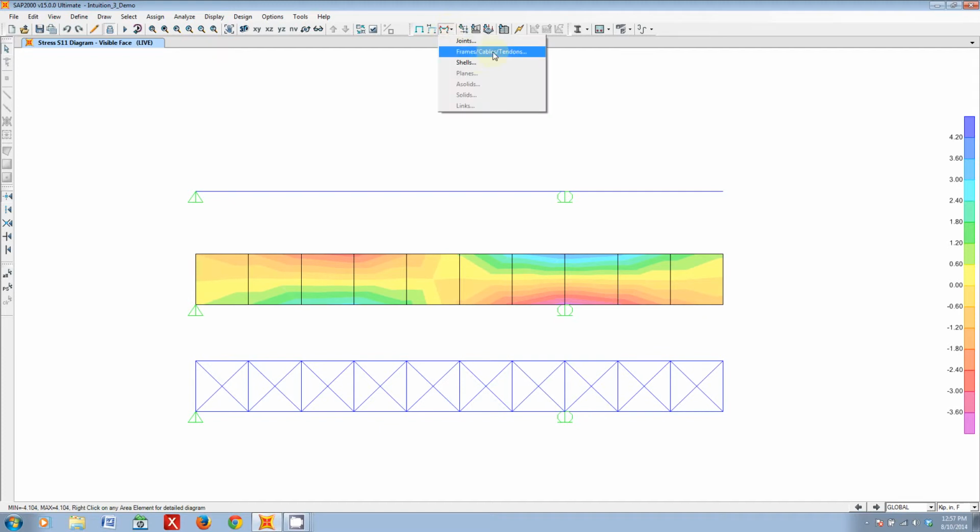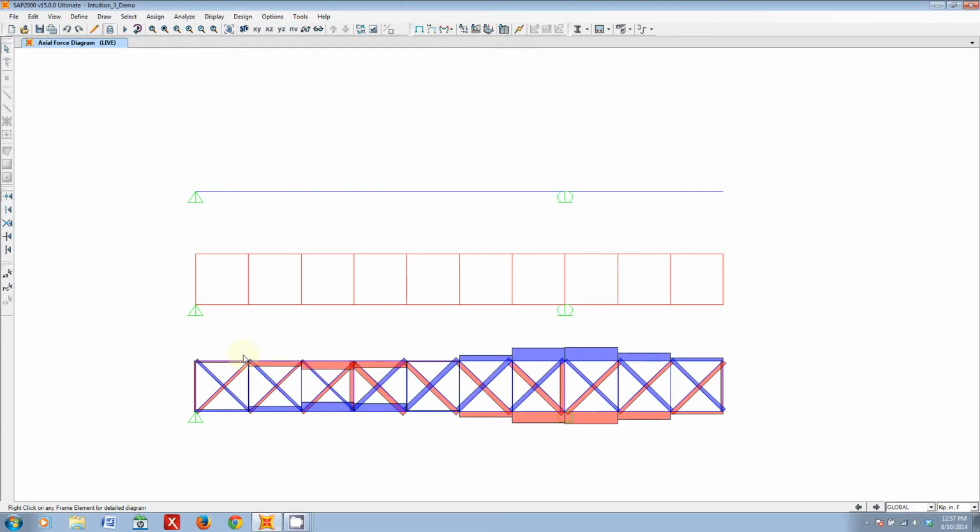And so that would have to mean that for our truss, we go from pretty much compressive forces in the top chords and now down to a transition region where we basically have no stress or almost no axial force in our top chords, because we're transitioning from that region of positive moment to negative moment. So in that transition region, there's no moment, which means that our top and bottom chords carry nothing. And then it switches from compressive loads in our top chords to now tensile loads in our top members, and then up to a maximum, and then it goes back down. Again, opposite is true on the bottom.